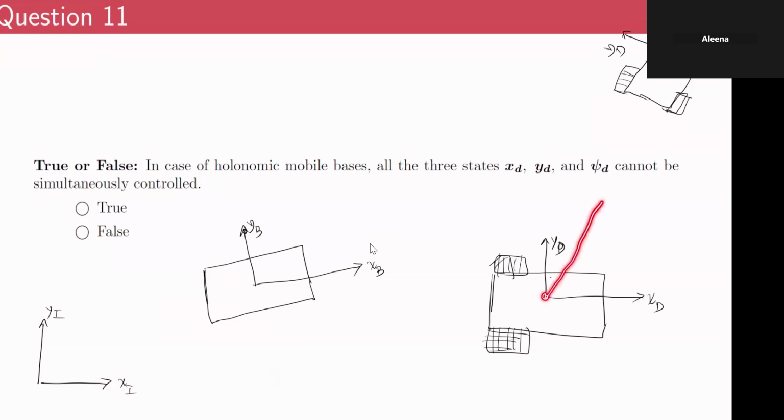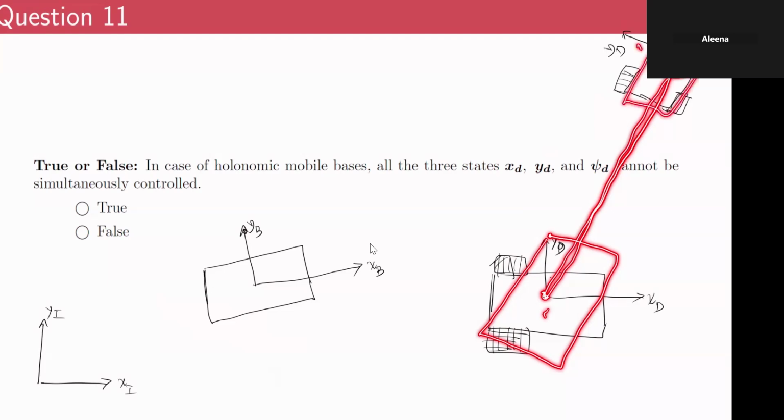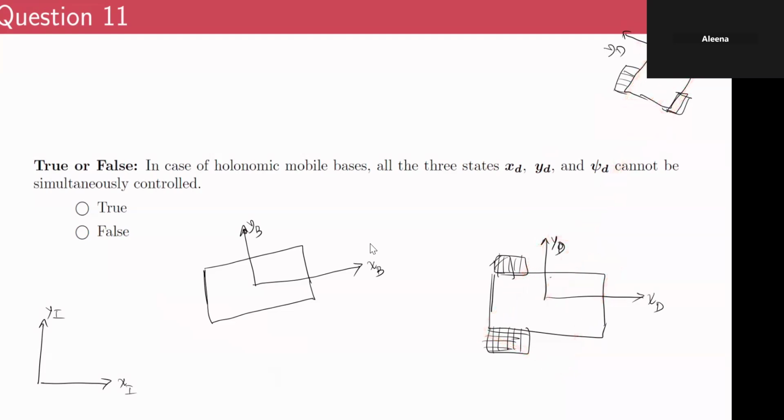First, it draws a line from the initial position to the final position. Then it rotates along that line of sight, and moves along the longitudinal direction. Once it reaches its final position, it realigns based on its rotational axis. That's how non-holonomic robots move.